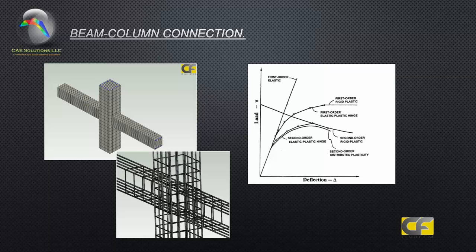But as I said, when this kind of structure, concrete columns and beams, is subjected to cyclic loading, it deteriorates. It loses capacity of withstanding load, and it loses capacity of dissipating energy. And one of the models where we can capture that behavior is what is called the first order rigid plastic, that is represented by plastic hinges.